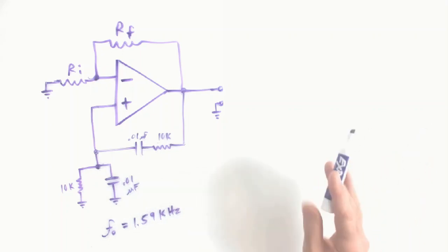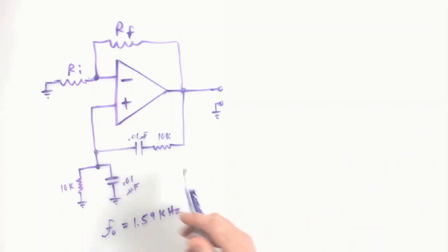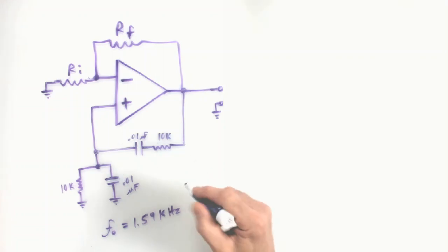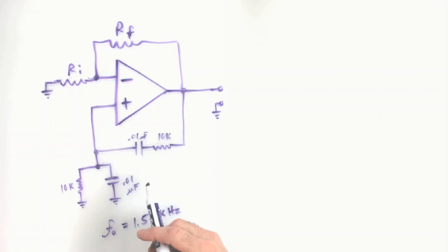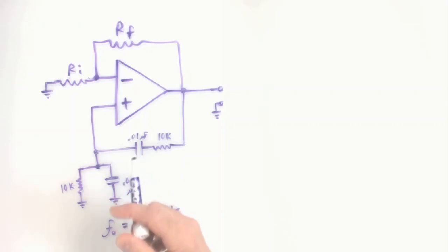And right here, I think it's important to emphasize, this is the whole thing of the circuit, because a lot of times I get asked by students, well, wait, where do I hook the signal generator? That's very different. There is no signal generator to be connected here. This is the signal generator. It's an oscillator. It produces a sine wave, so you will not be using a signal generator to inject a waveform like a sine wave into the circuit. There is no input for this circuit. This circuit generates. It is a signal generator by itself.